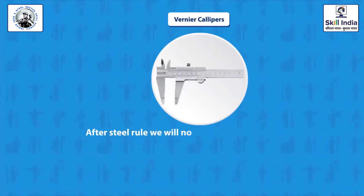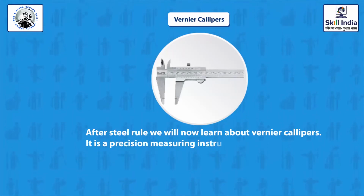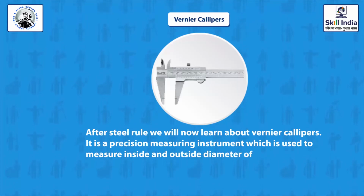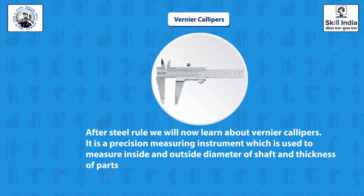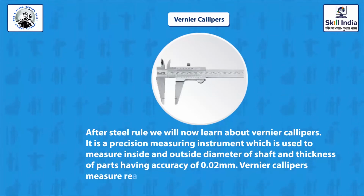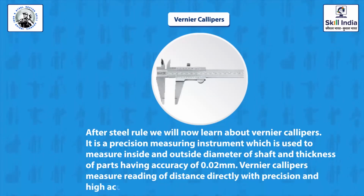After the steel rule, we will now learn about Vernier calipers. It is a precision measuring instrument which is used to measure inside and outside diameter of shafts, and thickness of parts, having an accuracy of 0.02 mm. Vernier calipers measure the reading of distance directly with precision and high accuracy. Now let us understand the different parts of Vernier calipers.